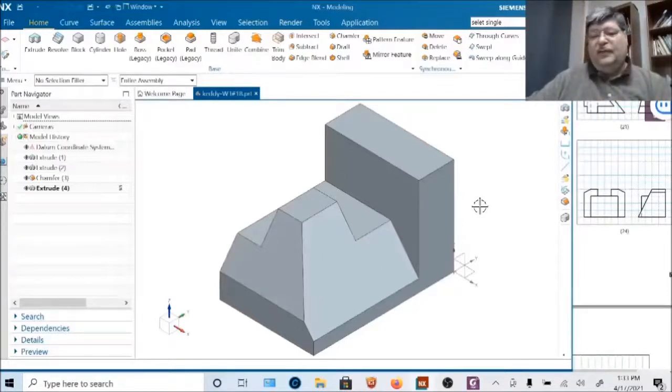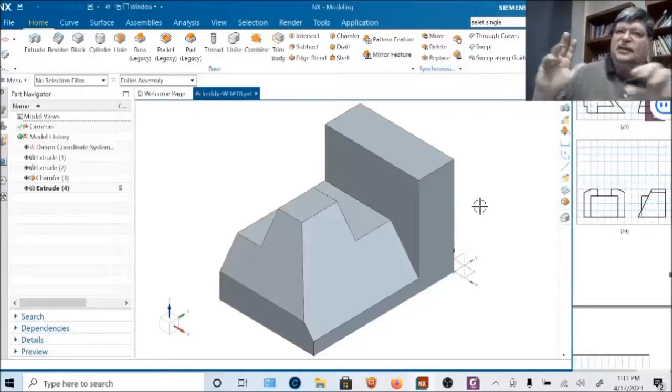You don't have to do them all 5 times, but you're just trying to learn a program. Maybe learn how to start the part by doing a frontal plane sketch first, and then do the model. The second time, start on the right side and do a sketch first, and then do the model.